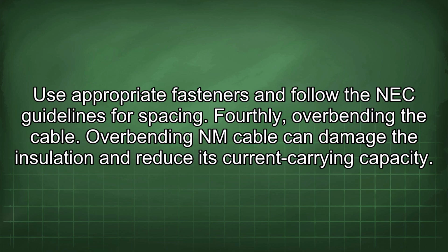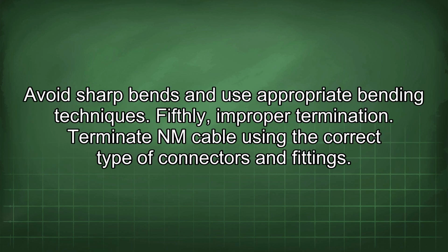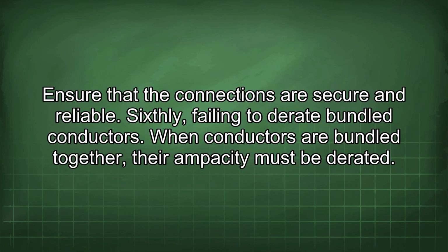Fourthly, overbending the cable. Overbending NM cable can damage the insulation and reduce its current carrying capacity. Avoid sharp bends and use appropriate bending techniques. Fifthly, improper termination. Terminate NM cable using the correct type of connectors and fittings. Ensure that the connections are secure and reliable.